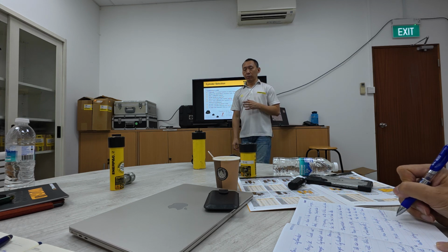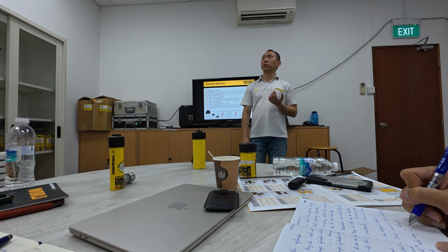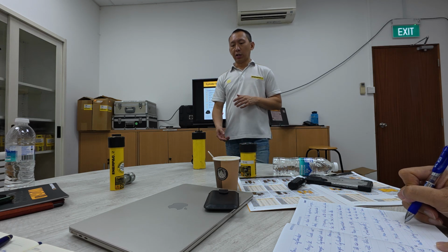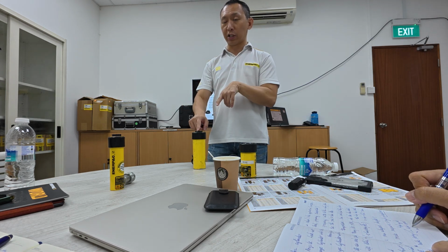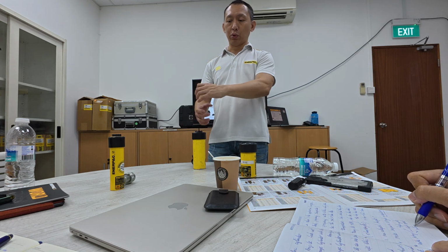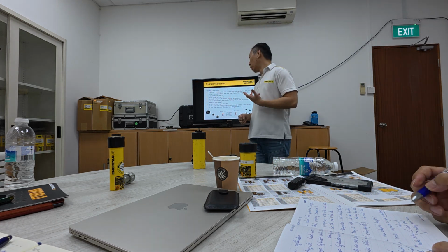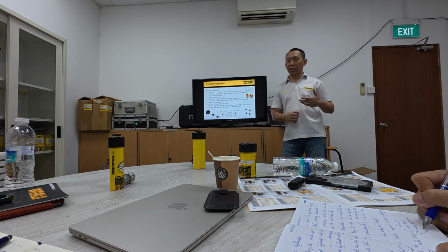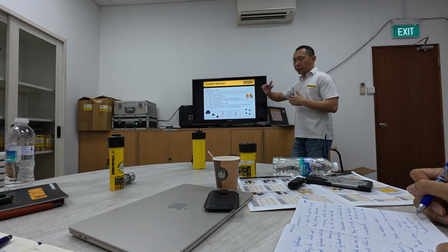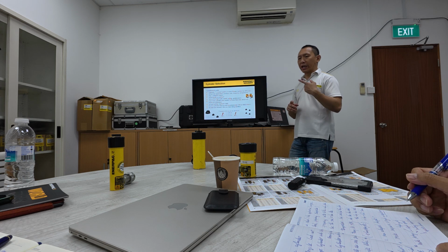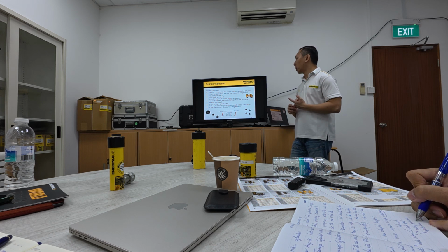Okay, we have come across applications where, for example, they use a cylinder inverted because they want to put an attachment over here to extend, and put their own attachment, because here there's a track over here, so that they can build some things over there. So they are always using it inverted. I'm not saying no, there are some applications that work this way. So orientation is very important because it will determine what type of cylinder you are using.